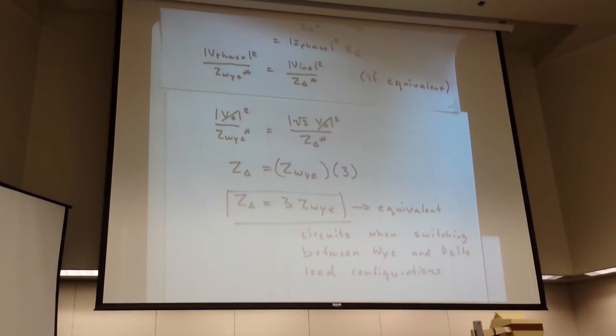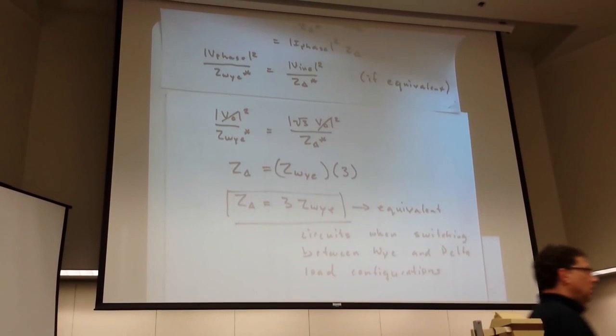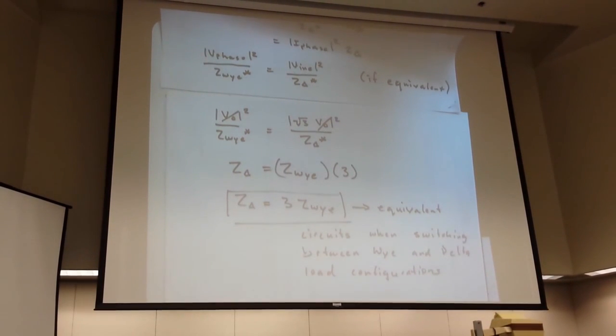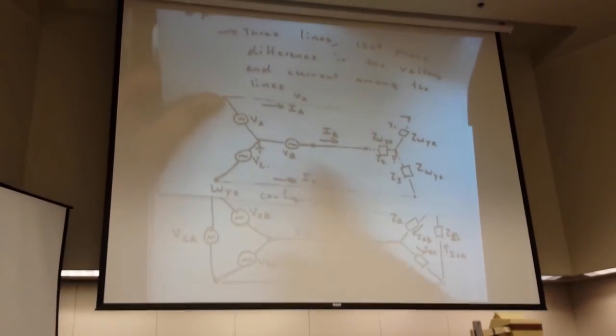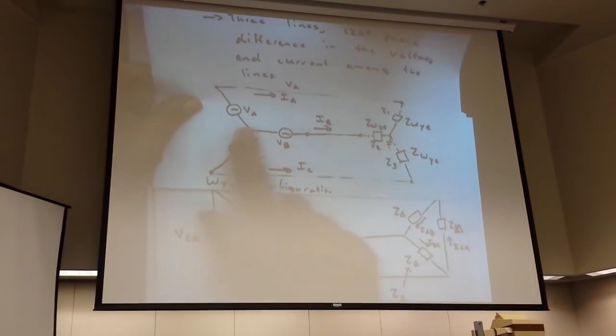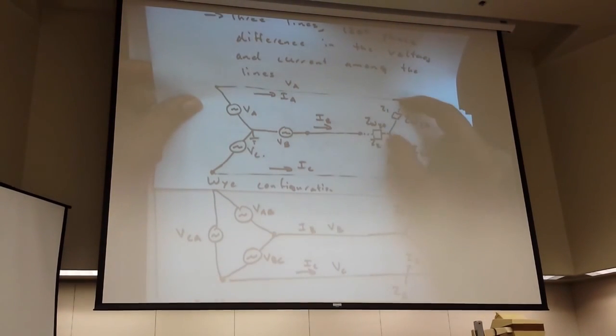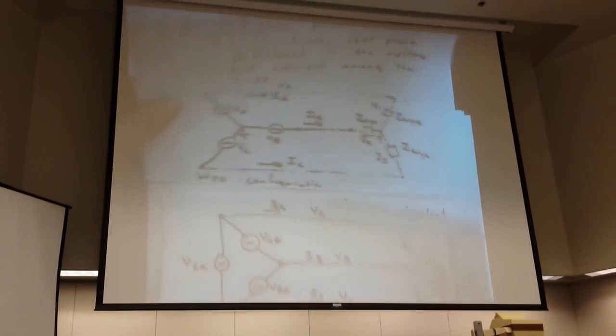And so we can connect then a Y load with a delta source. And if we want to analyze that, we convert one, either the delta source to a Y source, or Y load to a delta source. So either way is viable. Certainly here, if we want to analyze power, you have phase voltage, and that very quickly gives you information on power of the Y load comparably with the delta configuration.